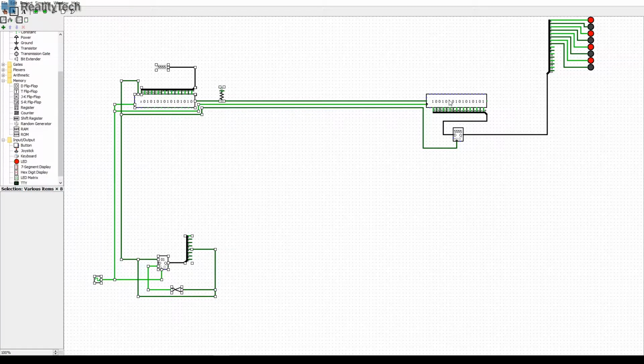There are 16-bit shift registers. You can cascade these, so you can quite happily put, let's pick up another shift register. So most shift registers have an output, so you can just shove the output of that shift register into another one, and you'll see now the data is clocking out.